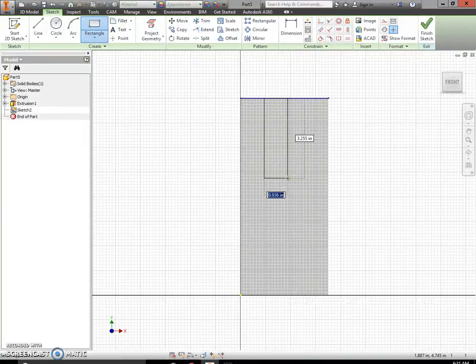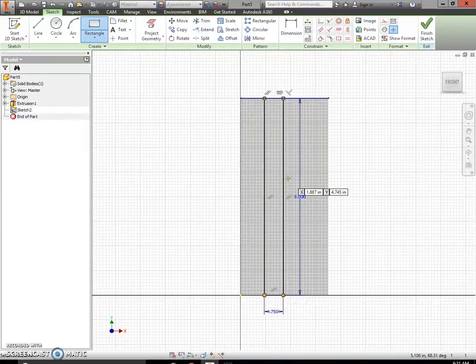So with my iPad open, the cover open, I'm going to measure the width of my iPad so that it can fit in the slot. If you need help with this, ask your teacher. When I measured mine, it is 0.75 for a width. So I'm going to type that into the box. Press the Tab key. The height of this rectangle for everybody is 8.0. And press Enter on the keyboard. Press the Escape key. Next I need to locate this slot to center it on my part.